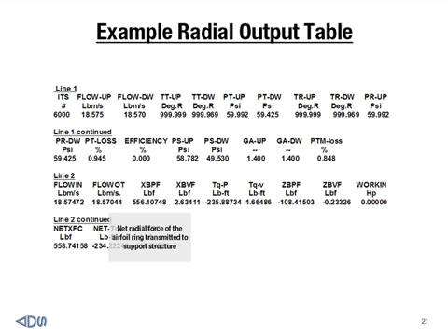This information provides the designer with very detailed information to execute airfoil preliminary structural analyses. And then later files can be output which would allow the structures people to basically paste these forces into any structural code for very, very detailed calculations.